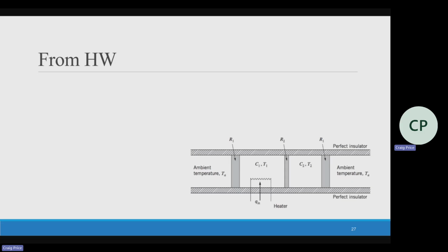But these are, because the temperature of the ambient is greater than the temperature of the inside, that's why I have to put T of ambient minus T. Yeah. And so when you plug that in there, you should be able to move T's to the side and get to a similar transfer function. Okay. So in that case, I go with this equation right here, and that's how I get the actual frequency. Yeah. That makes more sense. So you plug that in.